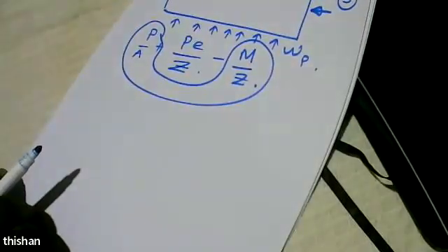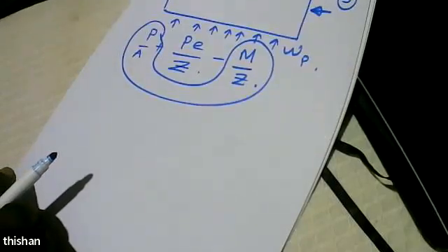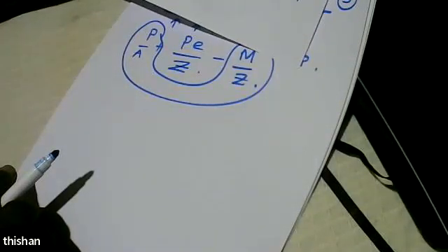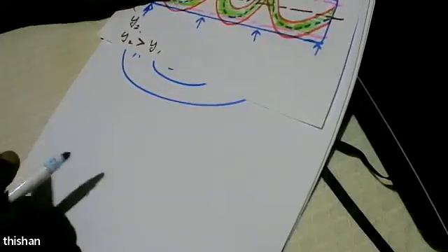This is extremely useful to explain what's going on in this type of situation. So now you can see a pre-stress force in a parabolic format is equivalent to an upward load W, where W is given by 8PE over S squared.